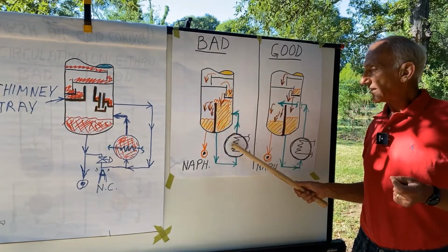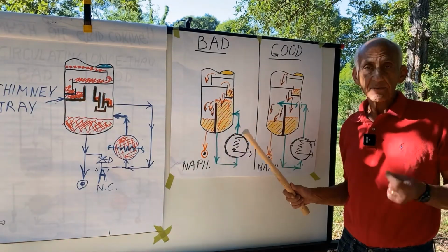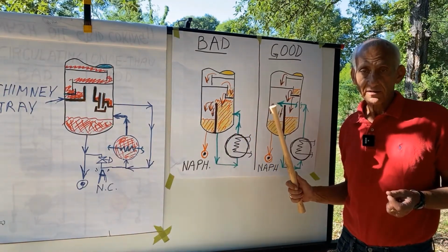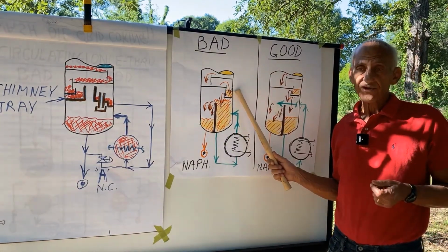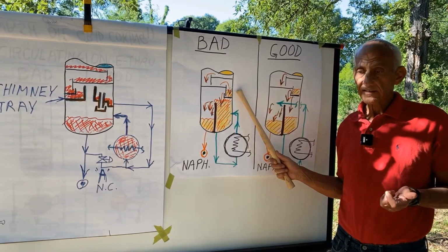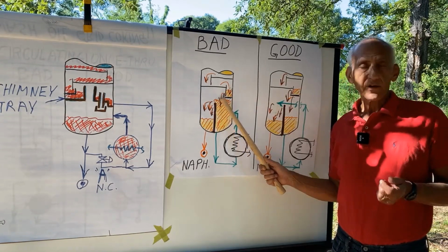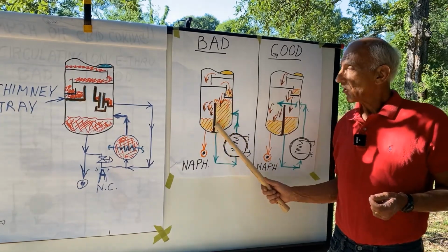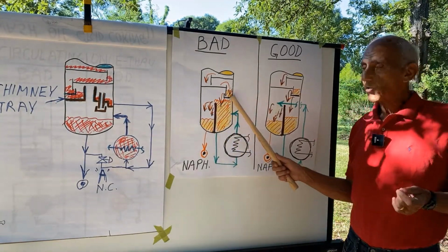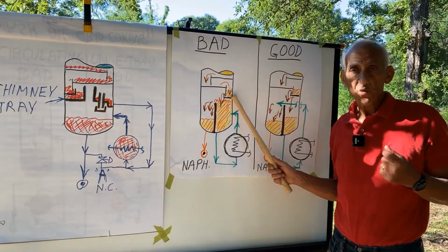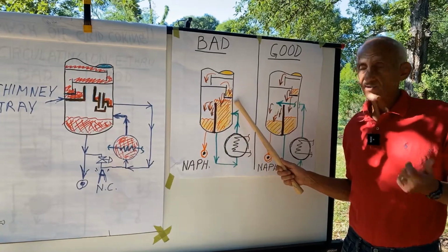I think you can see that I have back mixed the effluent from the bottom theoretical stage of the tower, the reboiler, with the liquid draining off the bottom fractionation stage in the tower itself. And this combined liquid then overflows the top edge of the vertical baffle onto the product or hot side and is drawn off.